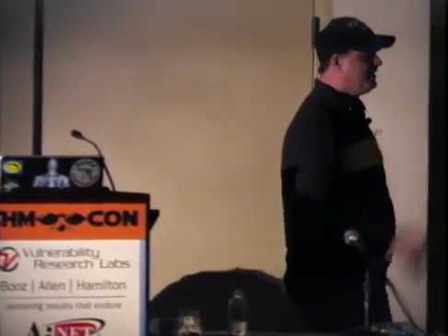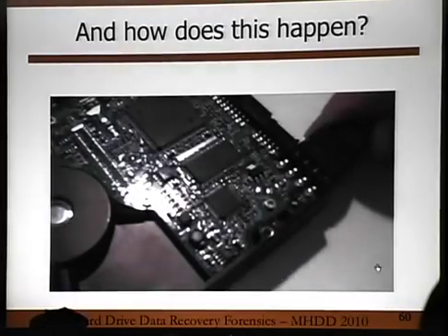Here's another thing. If you rip these off, don't plug it back into that power supply. That's probably the end of your drive. You will actually cause it, like, oh, it didn't spin up again. No shit, you just fried the damn thing now. You're going to blow the preamp on the head assembly or something. So plug this into something else, okay? Get something a little bit better that you're working on your workbench or something like that to at least make sure that you can read this. But that's bad news.